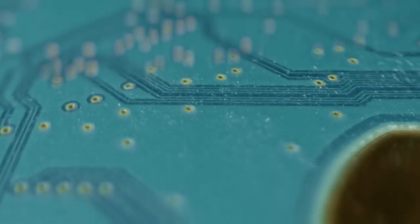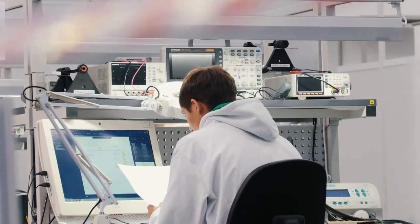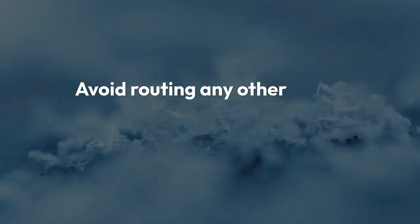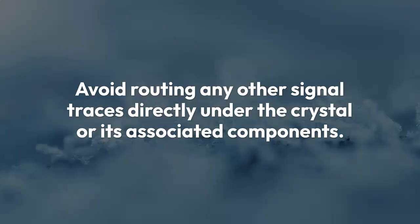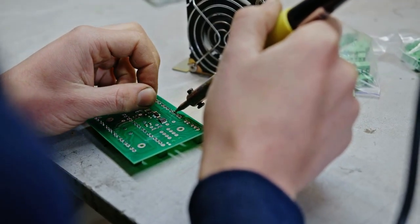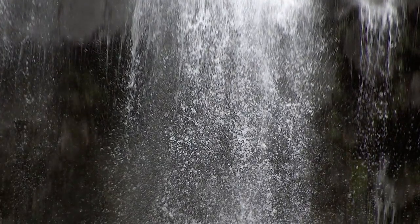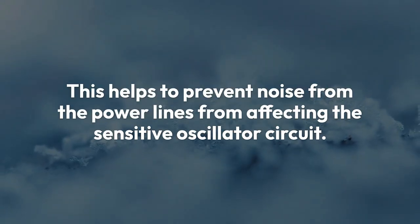Route a solid ground plane directly underneath the entire oscillator circuit. This provides a stable reference and shields the circuit from noise. Avoid routing any other signal traces directly under the crystal or its associated components. This prevents interference. Ensure your power supply to the STM32F4 is clean and stable. Good power supply decoupling capacitors near the MCU are absolutely essential. This helps to prevent noise from the power lines from affecting the sensitive oscillator circuit.